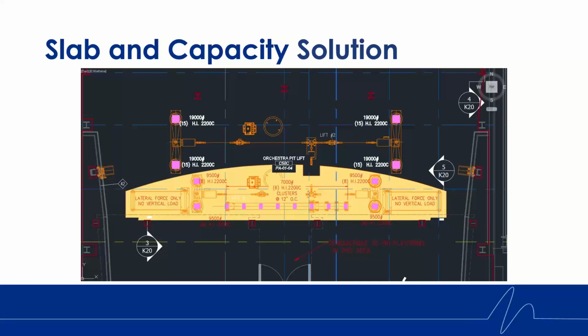In this project, the structural slab was specified for a load far below what the isolation slab with its supported equipment required. The slab thickness in some of the areas almost tripled due to weight and lateral forces, and the structural slab below required reinforcing. There was a year's worth of work in place, and the remediation was a big change order and delay in the project. The first change in approach to solving the loads was to change the isolator type from a jack slab to a rim rollout isolation material system isolated slab.